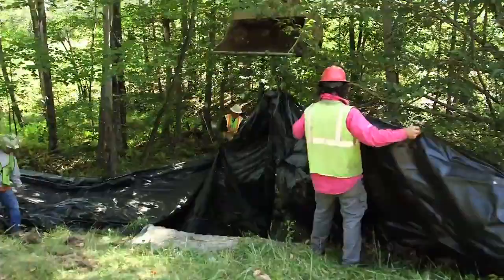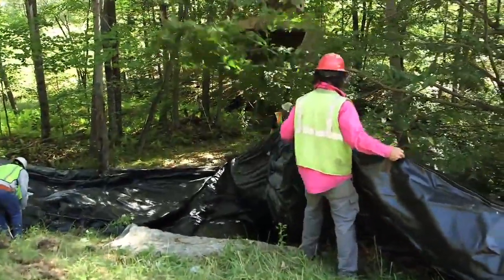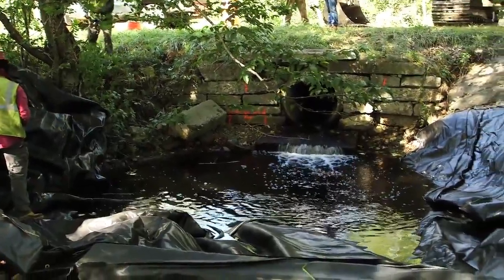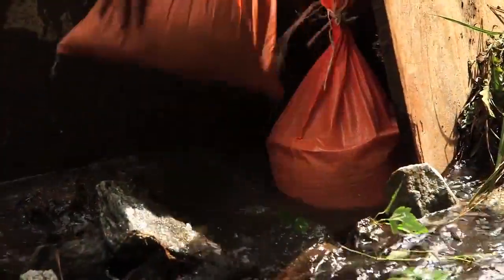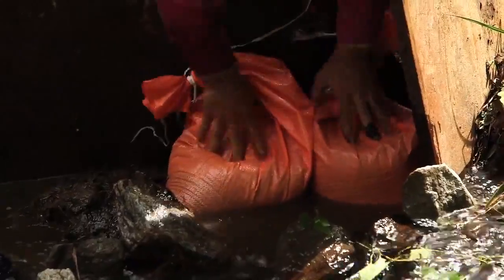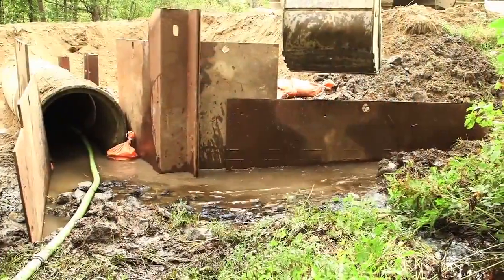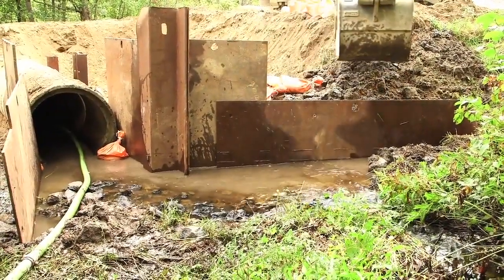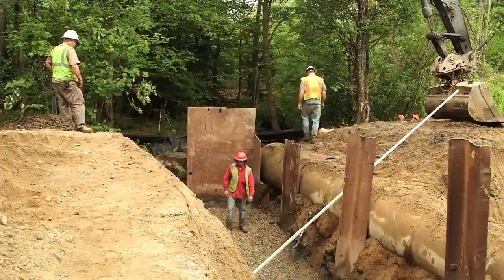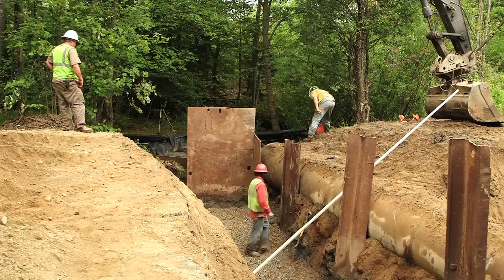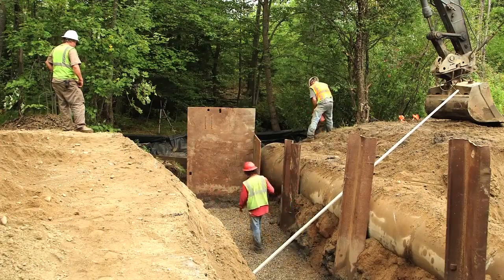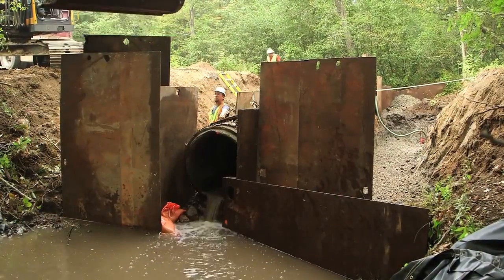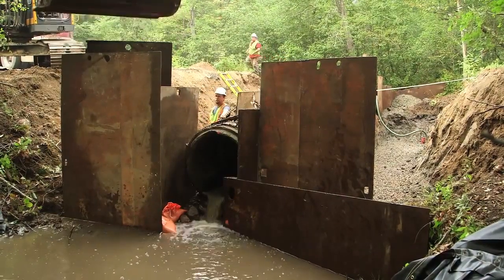Using an existing basin at the outlet of the culvert, the contractor installed a geotextile sediment barrier to help catch sediment. At the upstream end of the pipe, steel plates and sandbags were placed to direct all stream flow through the pipe and keep the disturbed work area out of the flow going through the pipe. On the downstream end of the pipe, steel plates were also installed to keep the stream flow out of the footing working area and minimize sediments from the working area entering the stream and sediment basin.